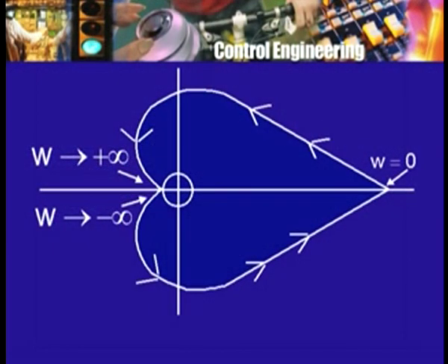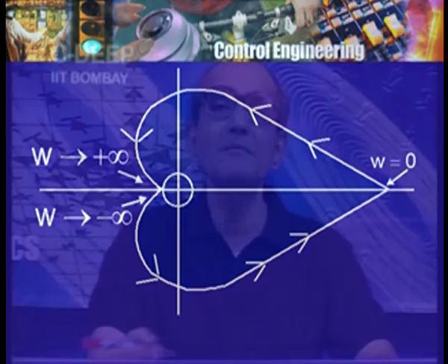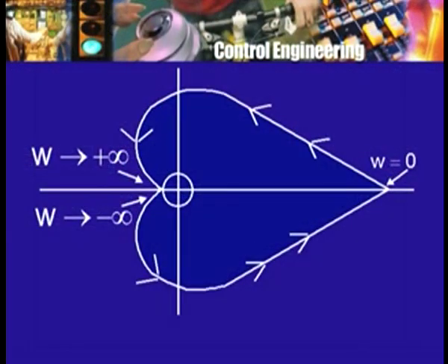And as is obvious, you can only apply frequencies up to a certain upper limit. If a frequency is too high for a system like a motor, it will not make any sense; the motor will hardly turn if the frequency is very high because of its inertia, the inertia of two kinds. So, there will be an upper limit on omega, maybe up to 10 kilohertz. In other words, the measurement points will end up somewhere here, and one is now extrapolating to go beyond that, trying to guess what will happen when the frequency is increased indefinitely.